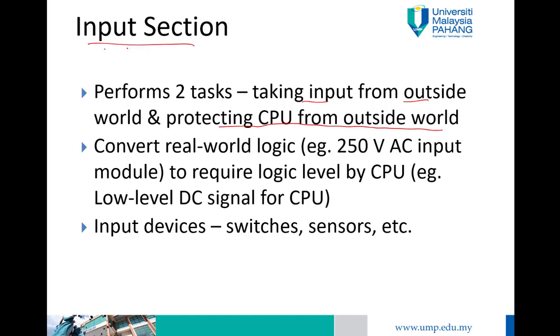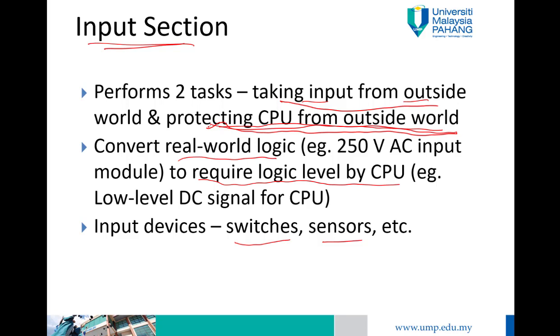It converts real-world logic to the logic level required by the CPU. Input devices, for example, are switches, sensors, etc. The input section must also be capable of detecting any unusual power or unusual voltage supplied to the PLC.